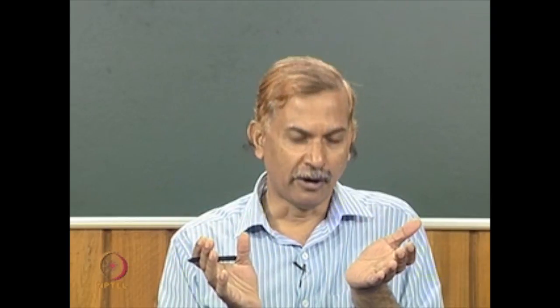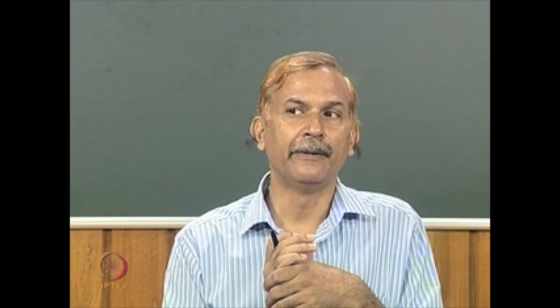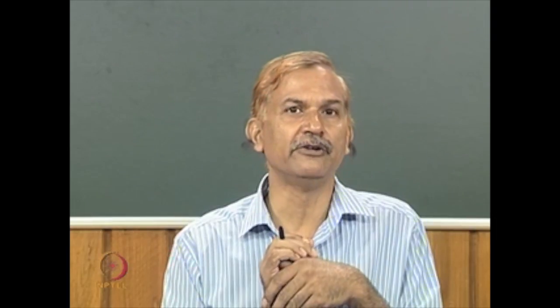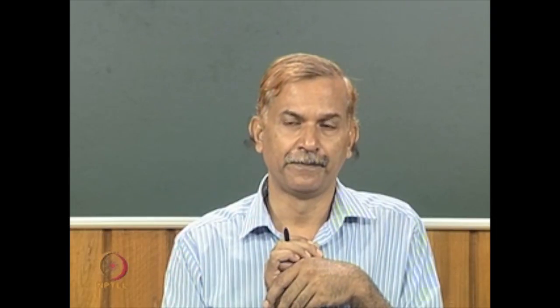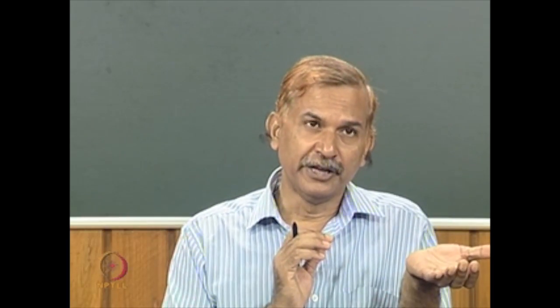we may need some algorithm or method to work with those BDDs. Once I give a Boolean function and you have chosen a particular variable ordering, you are going to construct the ordered BDD for that function, and you can construct it with the help of Shannon expansion of the Boolean function. But whatever you get, you have to check whether it is reduced or not, and if it is not, you have to construct the reduced ordered binary decision diagram. Already we have mentioned that we have 3 rules for the reduced BDD, and we can apply these 3 rules to the initial BDD.